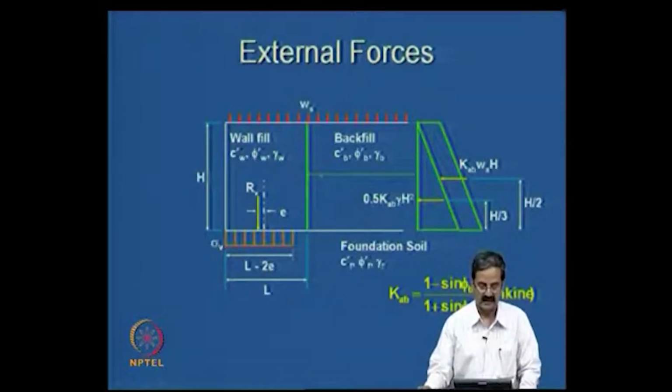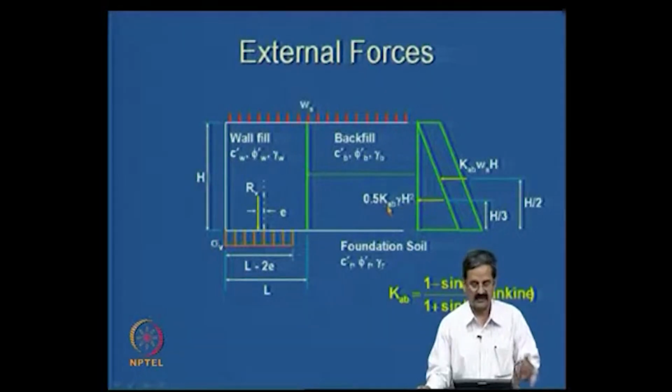We will see that. So, for example, this is the earth pressure diagram that we have to consider: half K_AB gamma h square, that is, 0.5 gamma K_a active, because this is for a geotextile, and what I am telling is a geotextile. So, half K_a gamma h square, and then this is h by 3 we assume, and the other one is Ws.